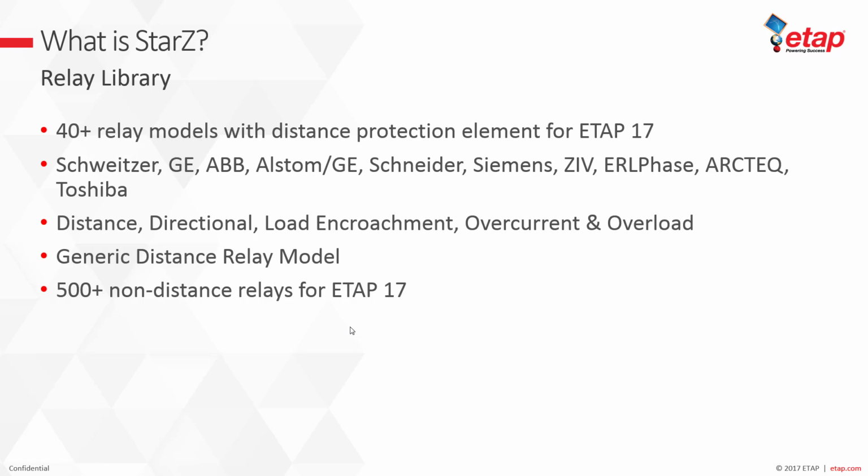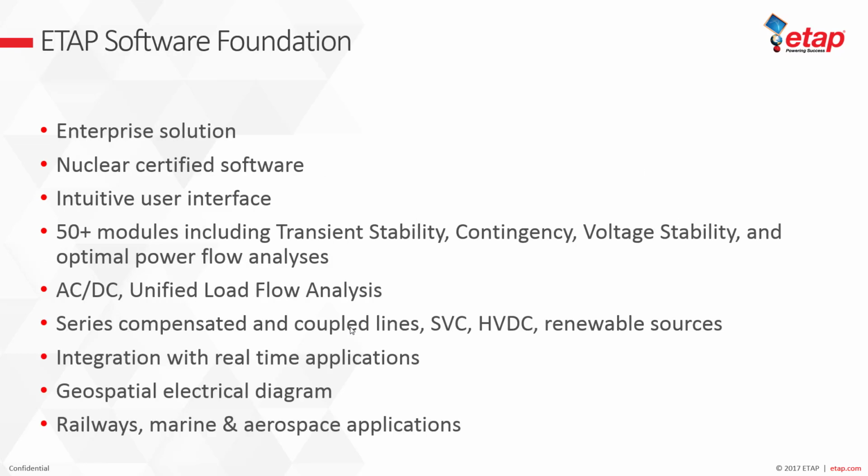We are providing the distance, directional, load encroachment, overcurrent, and overload functions for these relay models in the first release of StarZ, which would be ETAP 17. There will also be a generic distance relay model that can be customized through Relay Editor to simulate other generation protection relays. We also provide 500 plus non-distance relays for ETAP 17.